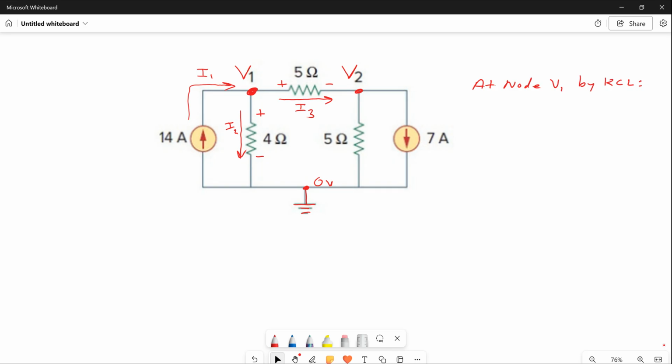So I like to look at conventional current flow that way. If you do the top line equation, at node V1, by Kirchhoff's current law, you get a plus I1 because it's gone into the node, a minus I2 because it's leaving the node, and a minus I3 because it's leaving the node, equals 0. That's a top level equation.